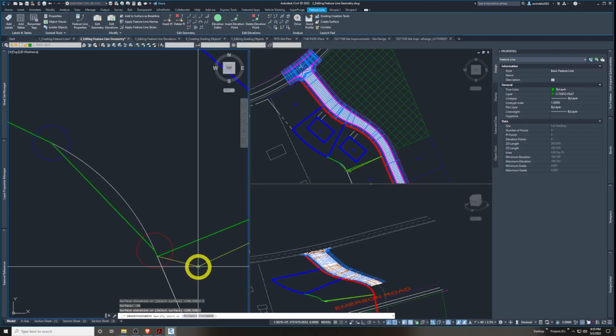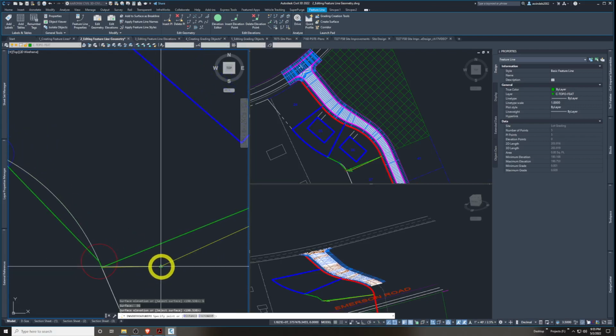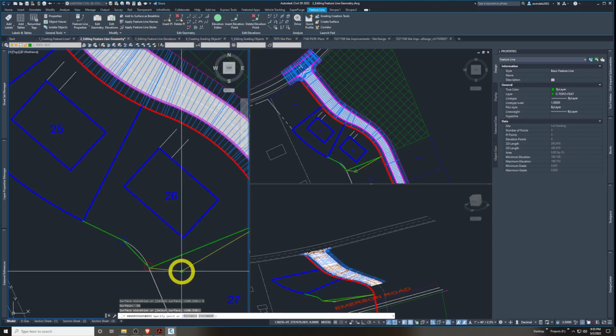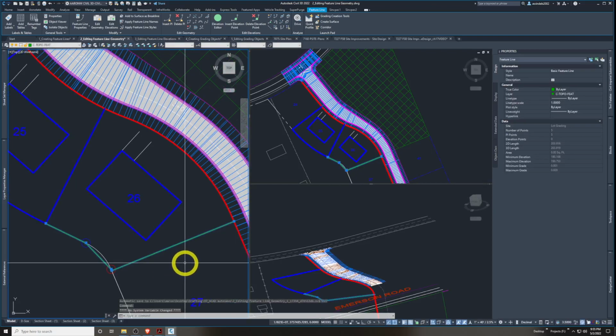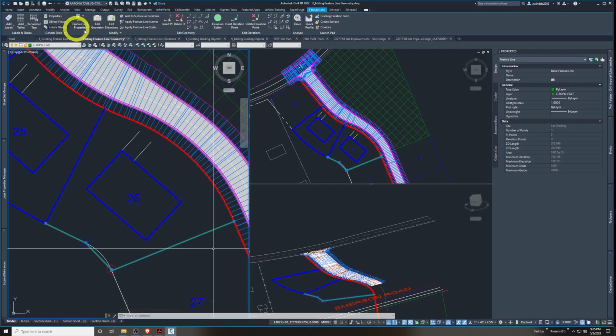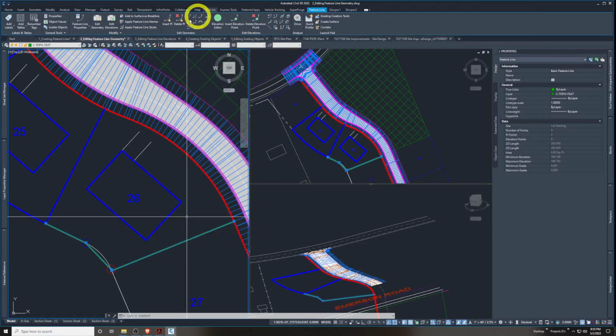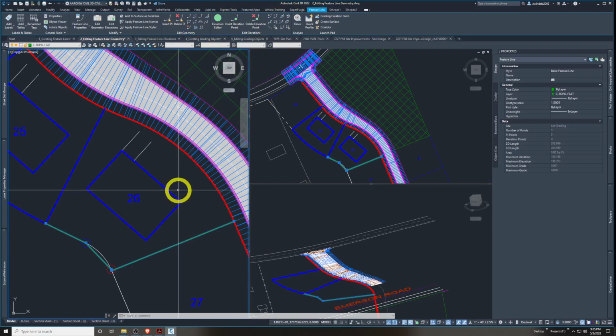We're going to talk about a missing curve now. So let's hit escape a couple times to clear this command out and go back to nothing in our selection set, but just the feature line. And when the feature line is selected, keep in mind your contextual ribbons, like we've been learning all semester, come up with all the awesome options you can use with the feature lines and grading objects and editing and groups and styles, adding them to surfaces and all kinds of things here. So no different, just a slightly different palette of options than we're used to seeing, feature lines.